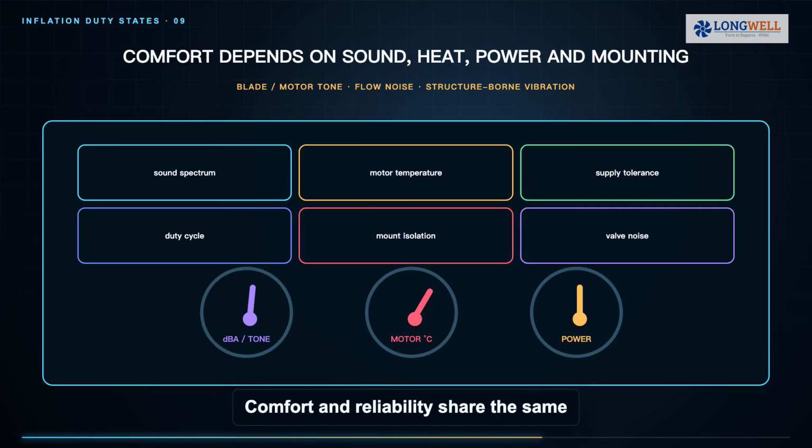Comfort and reliability share the same package. Blade and motor tones, valve hiss, structure-borne vibration, motor temperature, supply tolerance, mounting and duty cycle all affect the user experience. Measure sound as a spectrum and in the assembled product, not only as one bench number.